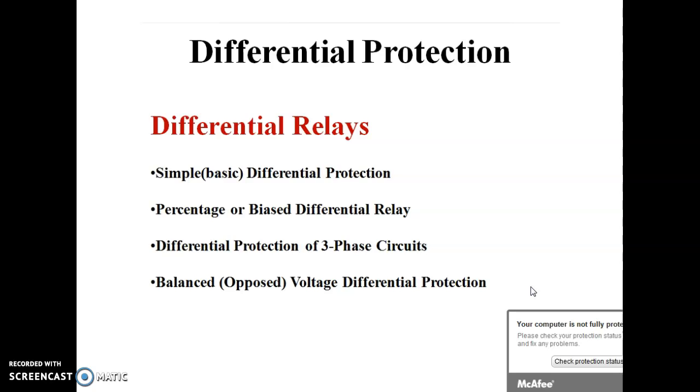While connecting the CTs, the main care we have to take is the dot polarity, that is, the polarity marks placed on the CTs. In order to trace the direction of the currents, we have to follow some rules. When the current enters the dot mark on the primary side of a CT, the current must leave the similar dot mark on the secondary side.